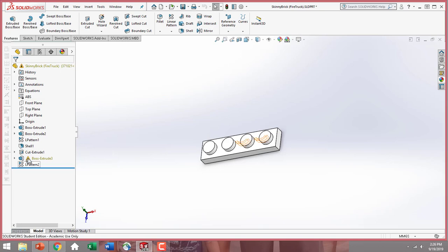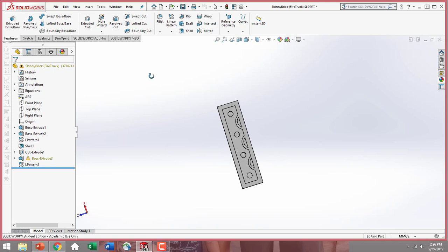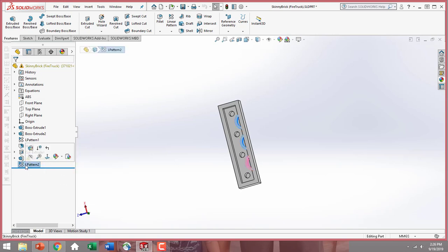Now you'll notice that you come up with an error on the bottom here. Let's flip that around. That is because with your 4x1, we no longer have this underneath annulus we first created. Instead, we have a smaller circle annulus. So we don't want to use the pattern or the extrude that we have been using for the rest of our Lego pieces. So go ahead and select that pattern.